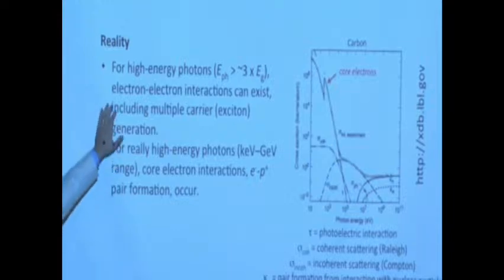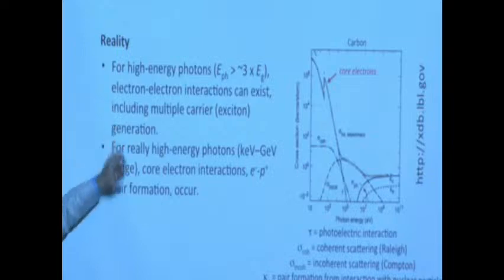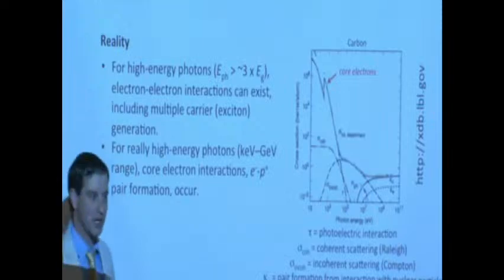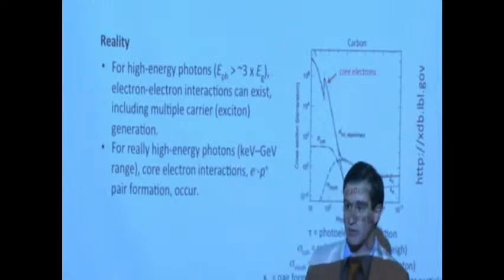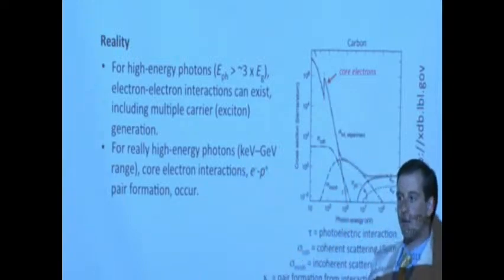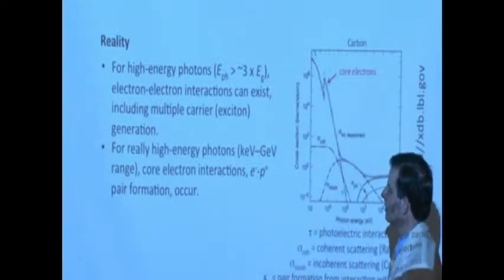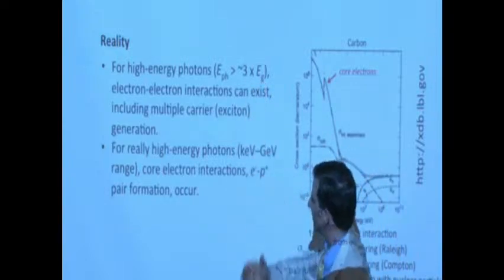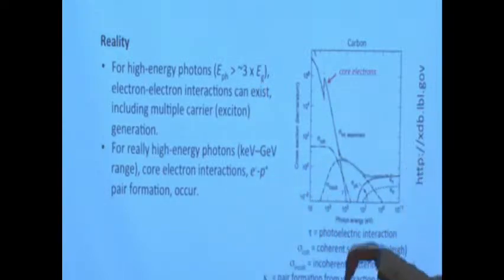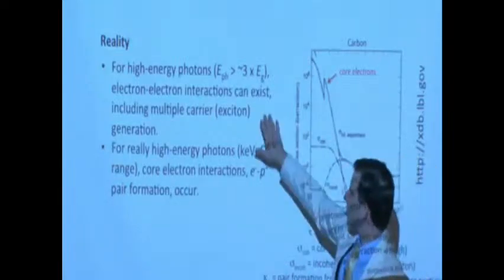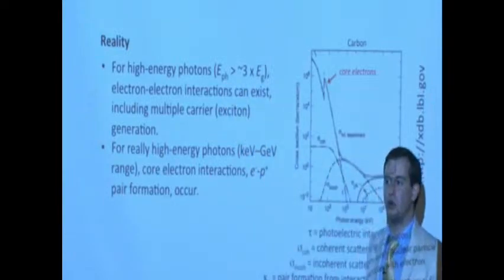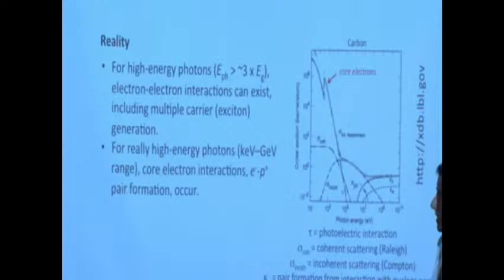So we have what's called multiple exciton generation, sometimes referred to as multiple free carrier generation, in semiconductors as a hot topic because folks would like to take the ultraviolet portion of the spectrum, the high energy, short wavelength portion of the solar spectrum, and use it to excite multiple carriers, one photon exciting multiple carriers across the band gap. There is or was some work, it was a hot topic for a while, it's kind of decayed a bit now. It comes in waves, it cycles, kind of like a plane wave. There is general interest in the field of how you capture these higher energy photons and convert them in some usable way instead of just having thermalization loss, instead of just having heat.